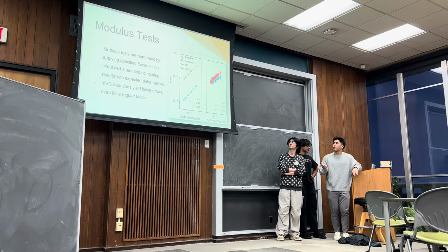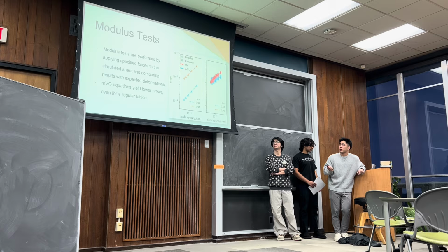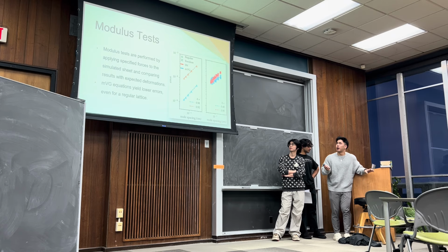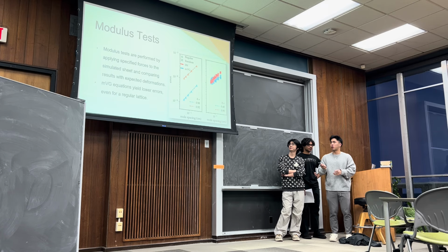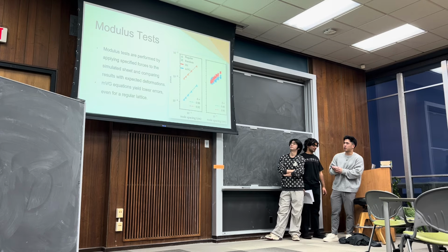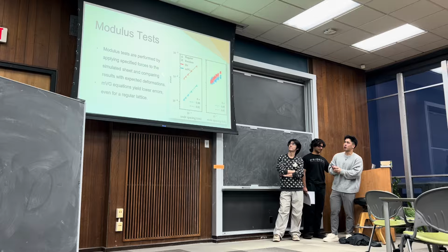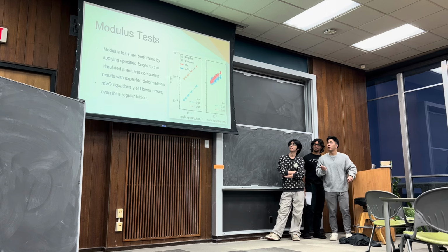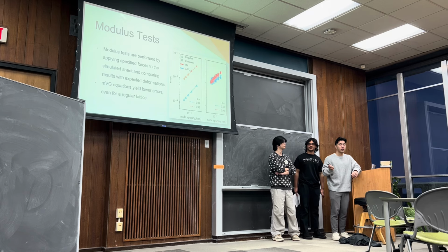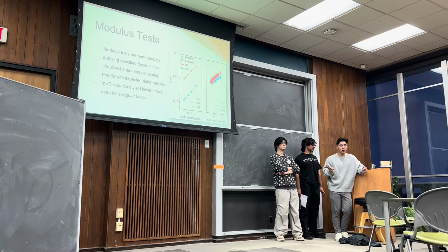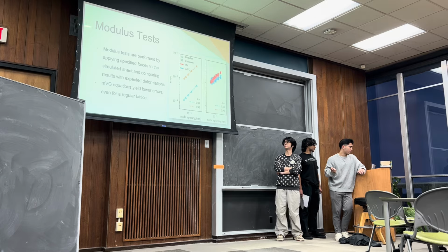And finally, we can see that they apply 4 different tests for the energy they're applying to the mesh, but they all have pretty much the same results. As you can see, as the knot spacing decreases, the y bar, which is the error, also decreases, and the relationship between those two is very linear. So they yield pretty good results, a nice first order convergence of the model to the theoretical continuous case.